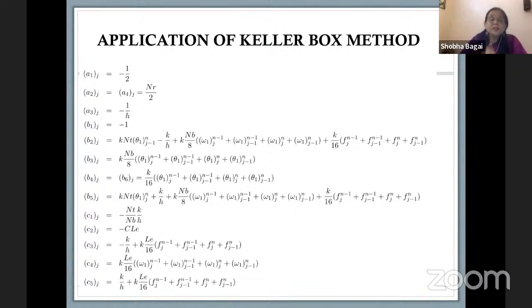Now, from the physical quantity, if you recall the conditions that we use, the temperature will go from TW in the non-dimensional form to T infinity, and TW is taken to be greater than T infinity. So the temperature is going to reduce. Since the temperature is going to reduce, I know that theta 1 is going to be negative, right?